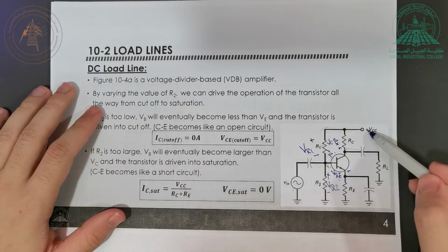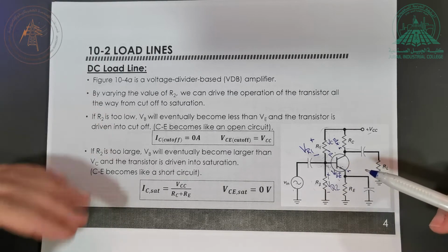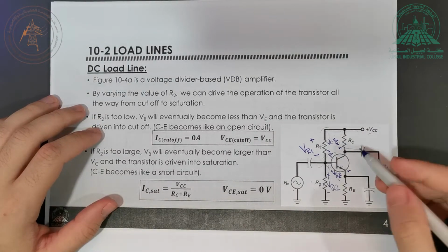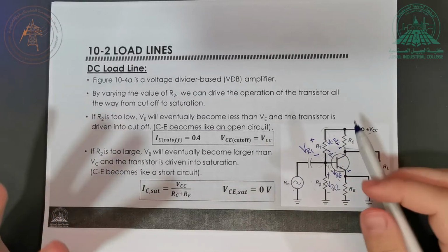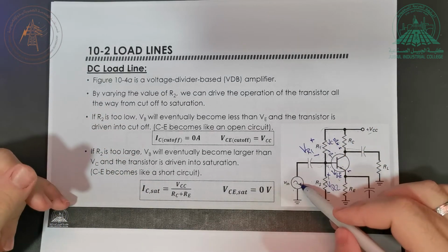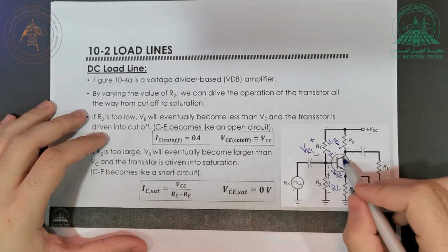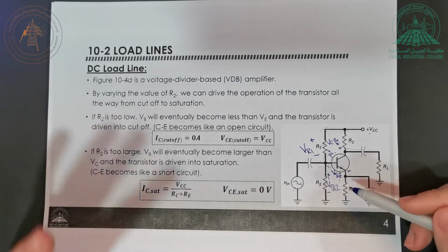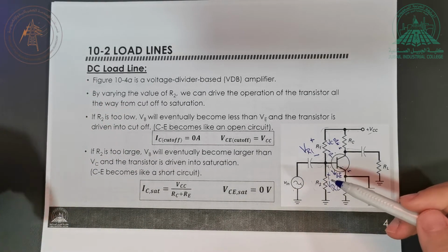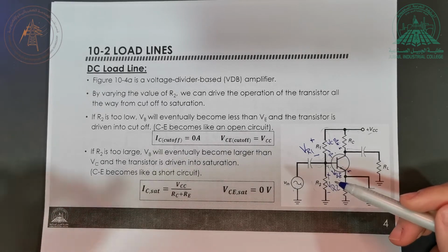This is the information. The DC source is to give energy and to bias that transistor to work, because it's not going to do the amplification job for free, right? The purpose of this is to supply the DC voltage for the transistor to work. That's why, when I look at biasing the circuit, I'm not interested in this. My focus now is how can I make this active. So I'm dividing this DC voltage between these things, so I can just ignore this and look at the circuit from a DC point of view.